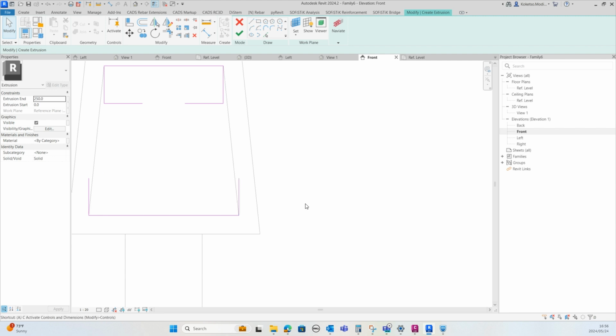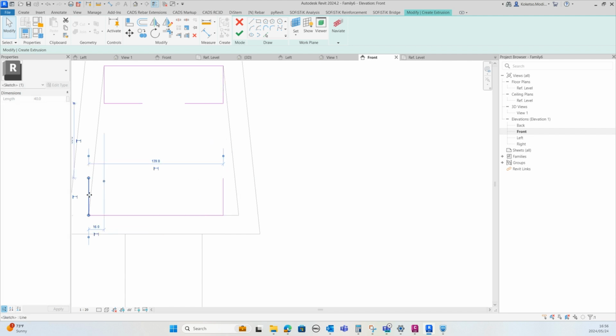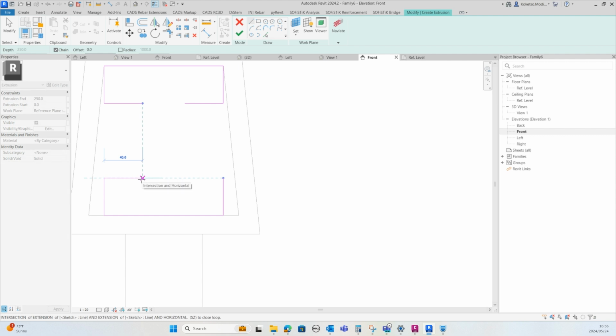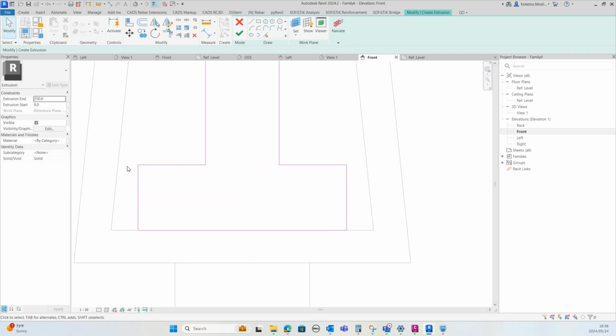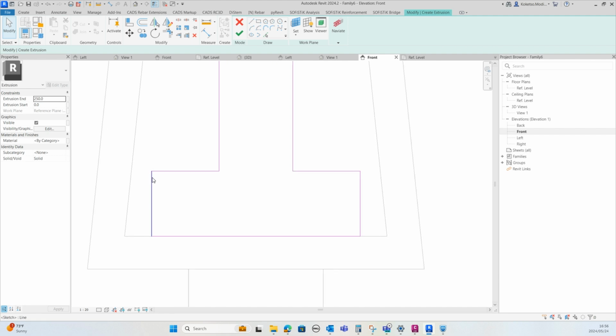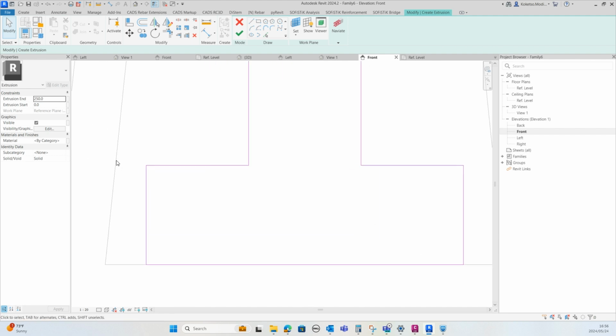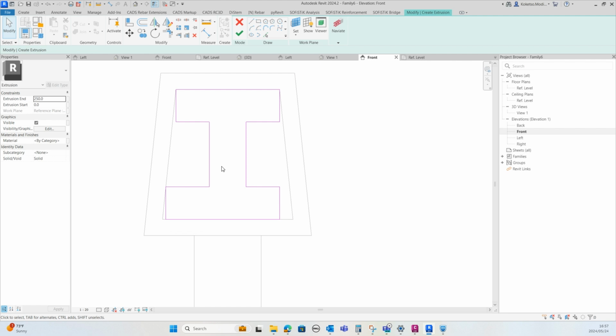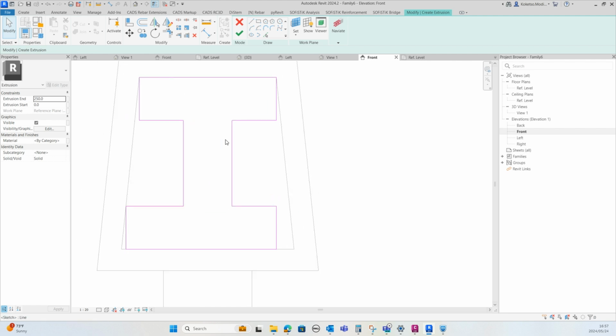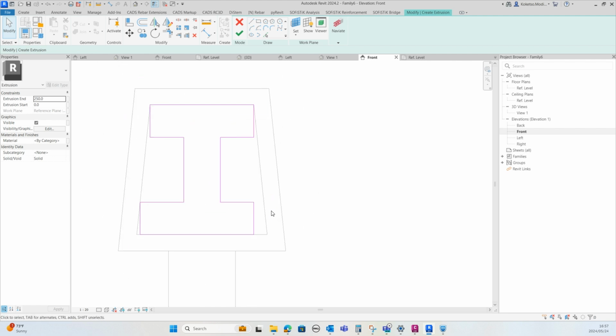So obviously it's going to clash with this, so I'm going to have to adjust it. So I'm going to move it like this, and then move it like this, and then take it to the right at 40, and then upwards like this, take it to the left at 40, and then upwards at 80 millimeters. So I want this to intersect with this line. So I'm just gonna drag this so that it provides stability inside the void of this aluminum element.